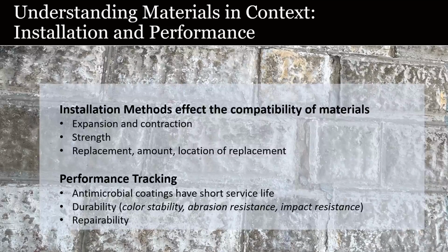Lastly, many new materials may appear to have specific performance advantages over their traditional counterparts, but these characteristics may only be designed to work for a short amount of time. It can be difficult to determine the durability of any material, but especially so for new materials with a shorter track record. Warranties are not the same as service life, and the repairability and durability of both the historic and potential replacement should be understood prior to any decision making.